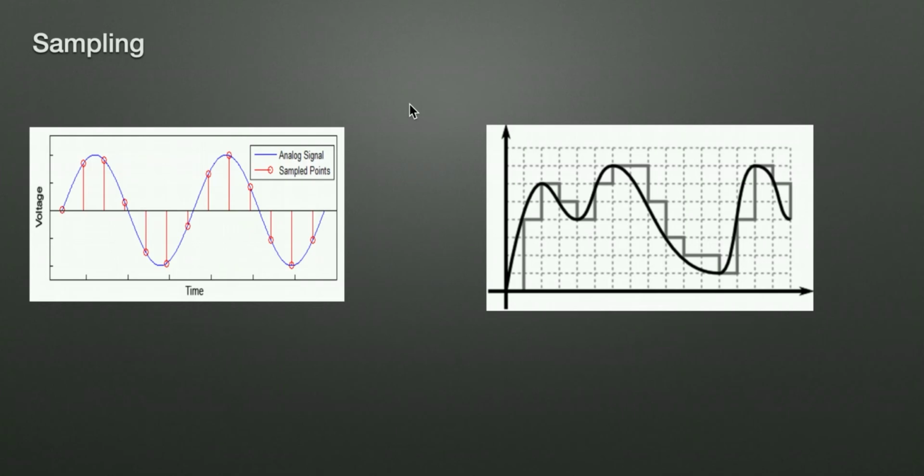That is what converts an analog signal to a digital signal. You take in only those points that you find necessary and store those values. Again, the more sample points you take in, the more detailed your image becomes, and the closer it is to the analog signal.